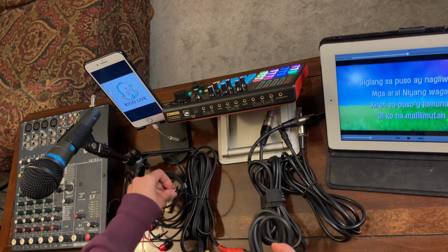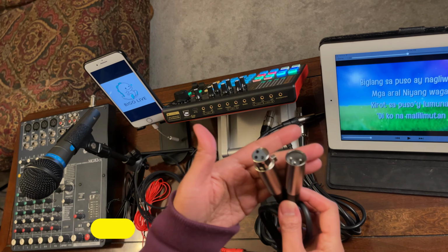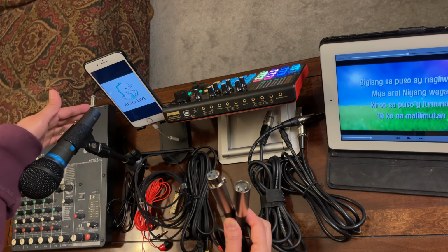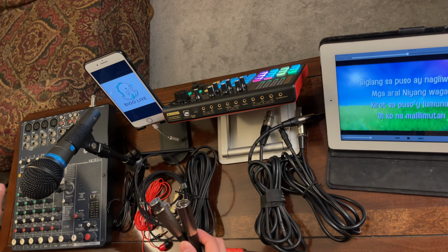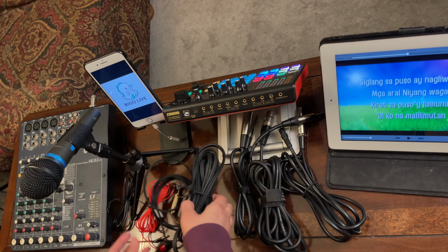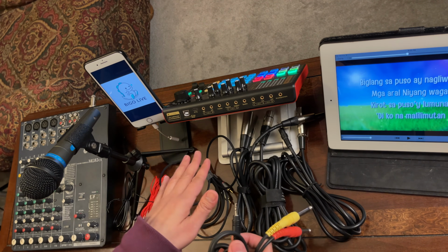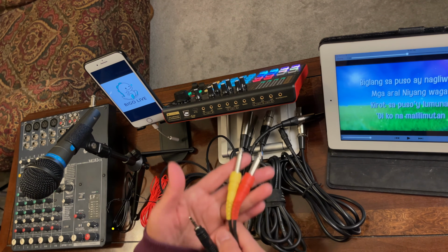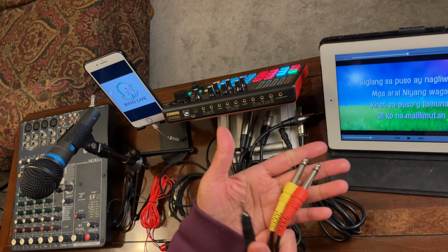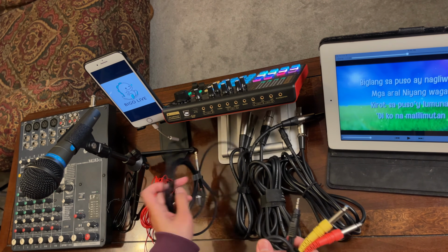And now if you are planning to connect your dynamic microphone to the mixer, then you will need this kind of cable. So XLR male to female, so you connect your dynamic microphone to here, and then to your mixer, and that is another option. Now this one here is if you will be connecting a mixer to the K300 Live sound card, you will need one of this. This is just an option. There should be another option, but I'll just show you this one. So this is to connect the mixer to the K300 Live sound card. I'll show you how to do that later.